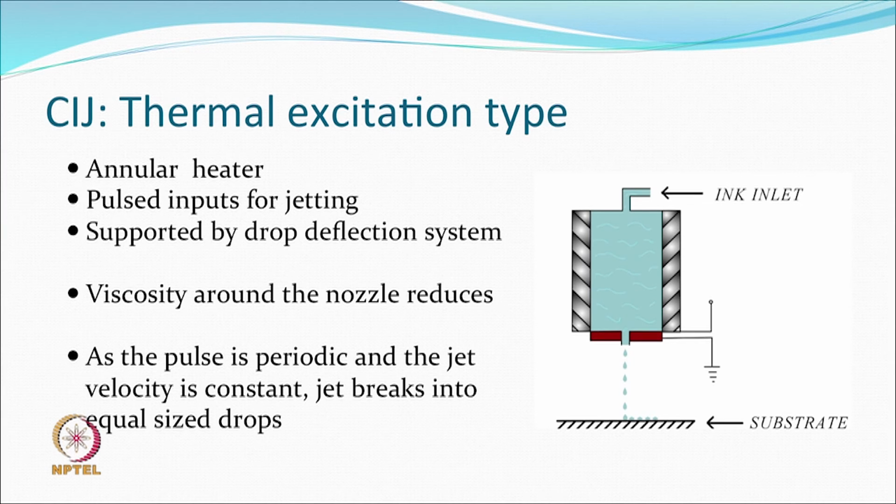So, another principle also people tried, instead of producing the drop by charge or another push, controlling the viscosity of the ink near the nozzle. So, near the nozzle you control the viscosity. You can appreciate the viscosity of the ink is such that unless and until it is pushed, it will not come out of the nozzle on its own. You have to do something. So, once something was being done, there was pushing through, let us say, a pump called a piezoelectric pump or something like that, and then charging and making it smaller and working it out.